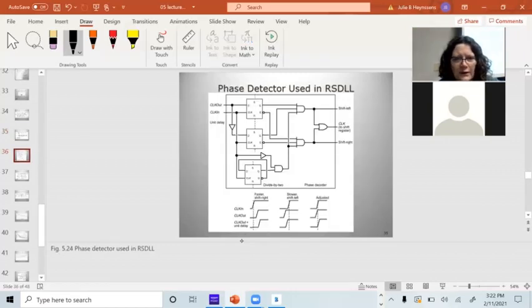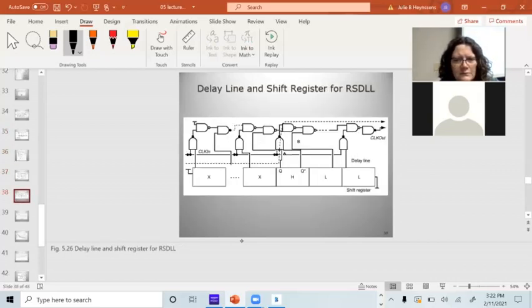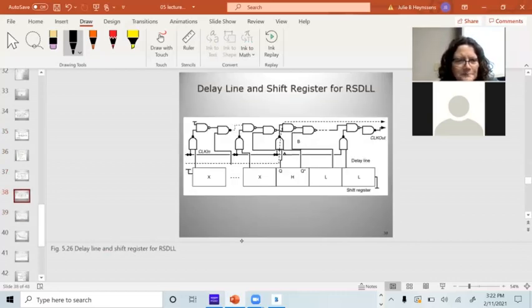There was something in here I didn't want to talk about. It's a phase detector. Black magic, PLLs. Basically what they're doing is they're using analog circuitry off the clock edge to generate an analog delay that's a quarter of a clock cycle away.